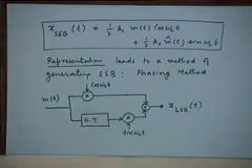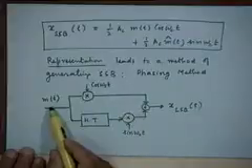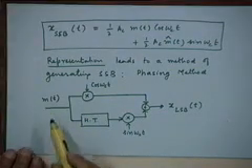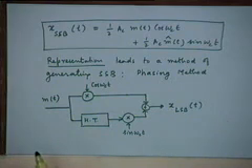Remember, an ideal Hilbert transformer will have to effect a minus 90 degree phase shift for each and every frequency component in the bandwidth of the message signal, right? Starting from f equal to 0 to f equal to B, whatever is the bandwidth. But such an ideal Hilbert transformer is also not easy to realize, right?